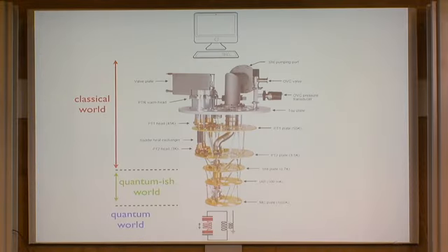To take a little bit more specific picture of what I mean by that, this is a picture of a completely empty dilution refrigerator, or at least the insert of it that our experiments happen in. And our experiments have to be at the very bottom of this, down where it's 10, 20 millikelvin. Although there's all these cold stages in between, anything that's not significantly less than a quarter Kelvin, say, when you're working in the 4-8 gigahertz band, is pretty classical. So it doesn't just have to be cold, it has to be extremely cold.